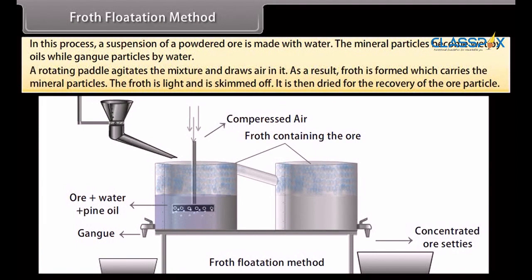A rotating paddle agitates the mixture and draws air in it. As a result, froth is formed which carries the mineral particles. The froth is light and is skimmed off. It is then dried for the recovery of the ore particles.